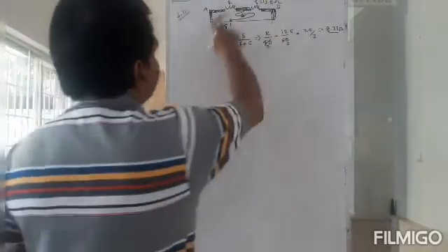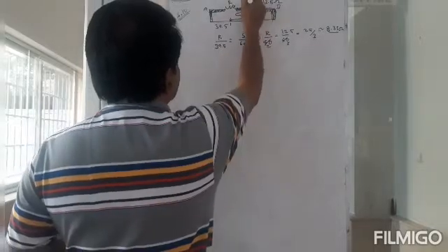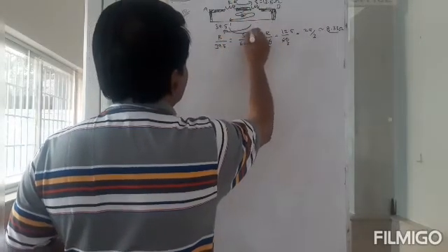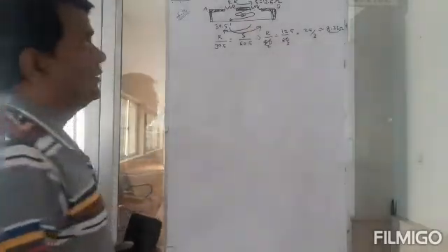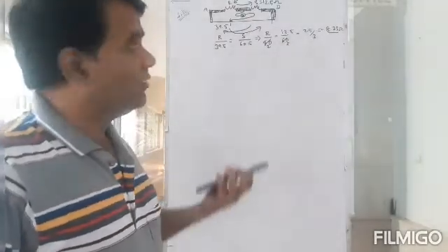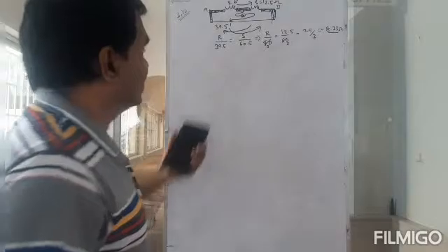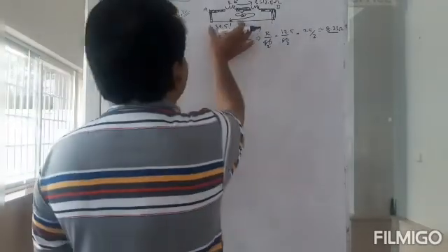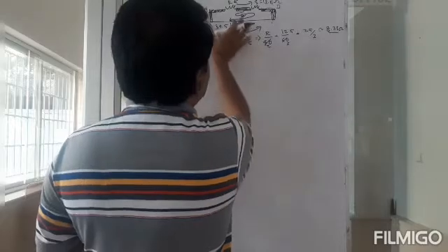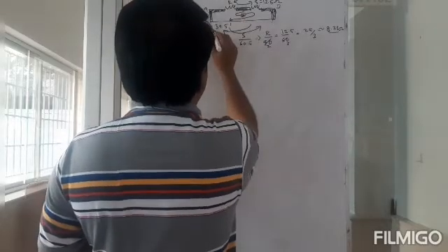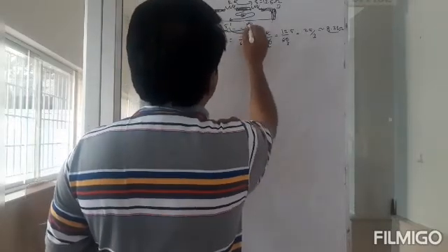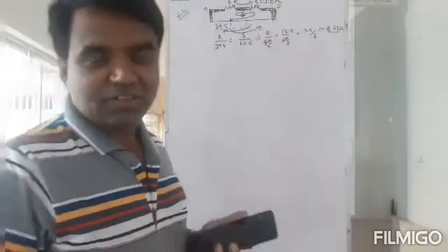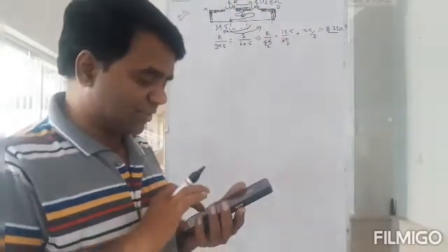Okay? So if you are interchanging this, if S comes here and R goes there, then this length will come here and that length will go there. That's about it. Okay? So that's all. Nothing else will change. So the balance point will be shifted. Right? Instead of 39.5, it will be 60.5. That's it. From A, it will be 60.5. From B, it will be 39.5 only, if we change it. Not much change. Nothing else will change.